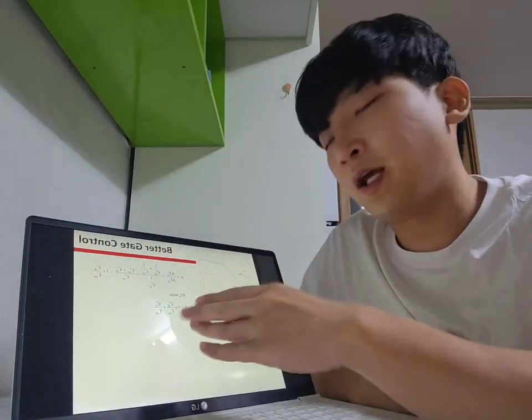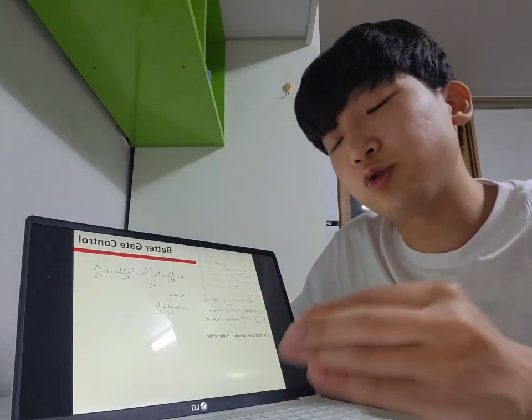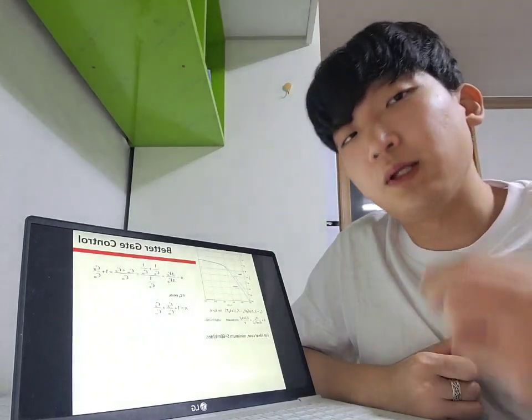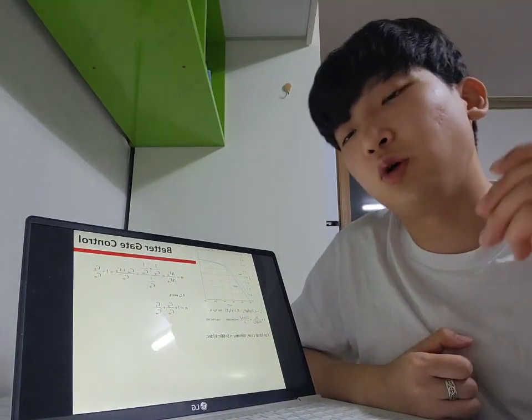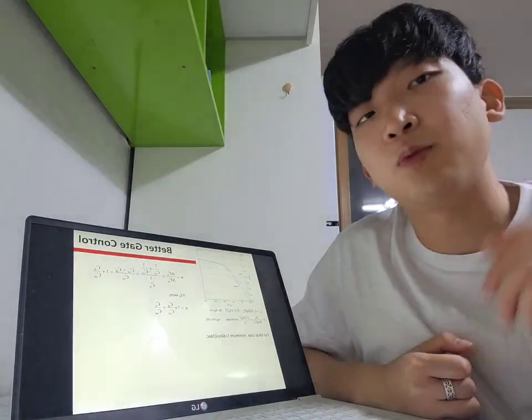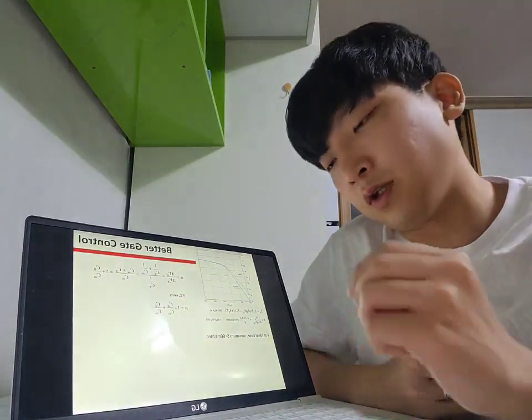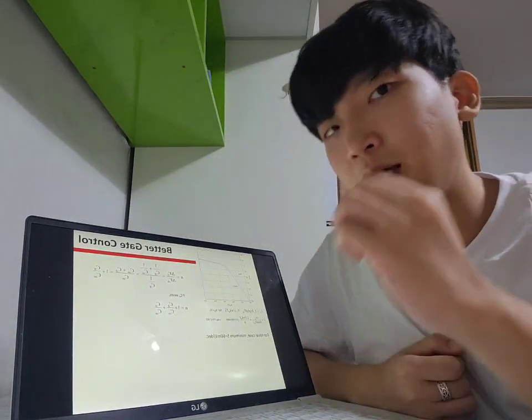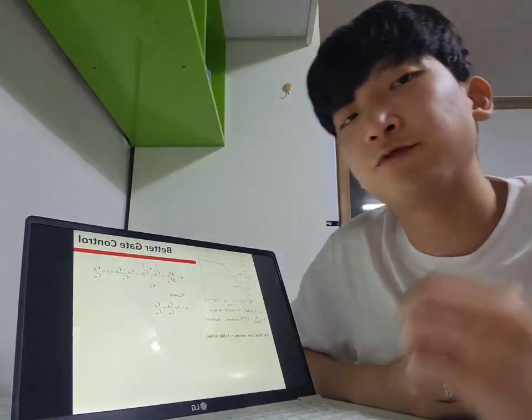It means the n will go closer to the number 1, and that means the subthreshold swing will go directly to the Boltzmann tail. So we can see that FinFET has a very good subthreshold swing.